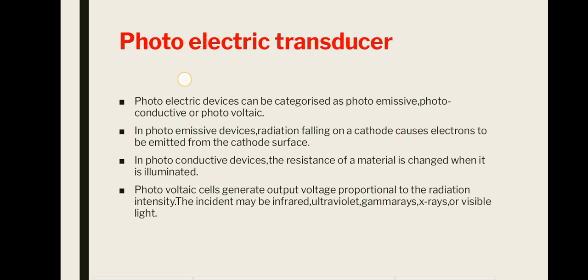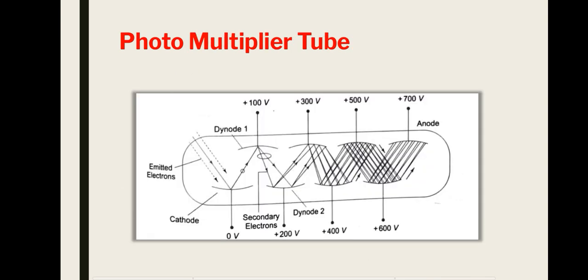Magnetic fields affect the photomultiplier because some electrons may be deflected from their normal path between the stages and therefore never reach a dynode or the anode. Hence the gain falls. To minimize this effect, mu-metal magnetic shields are often placed around the photomultiplier tube.